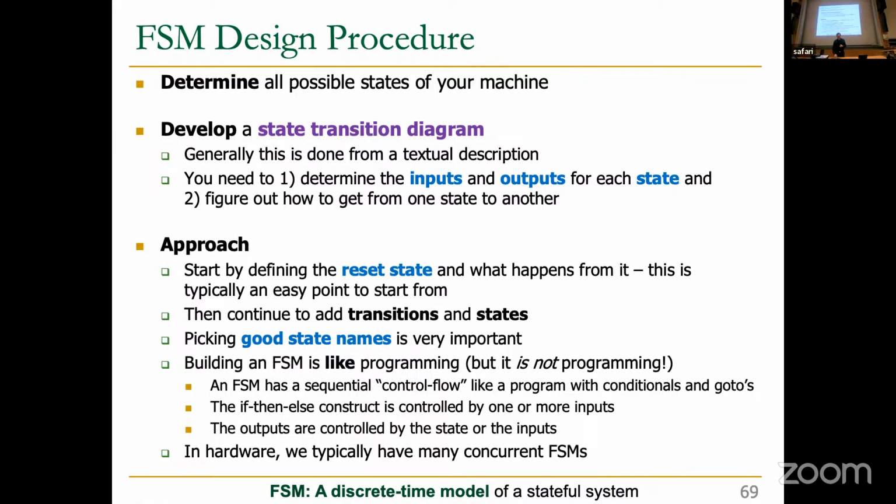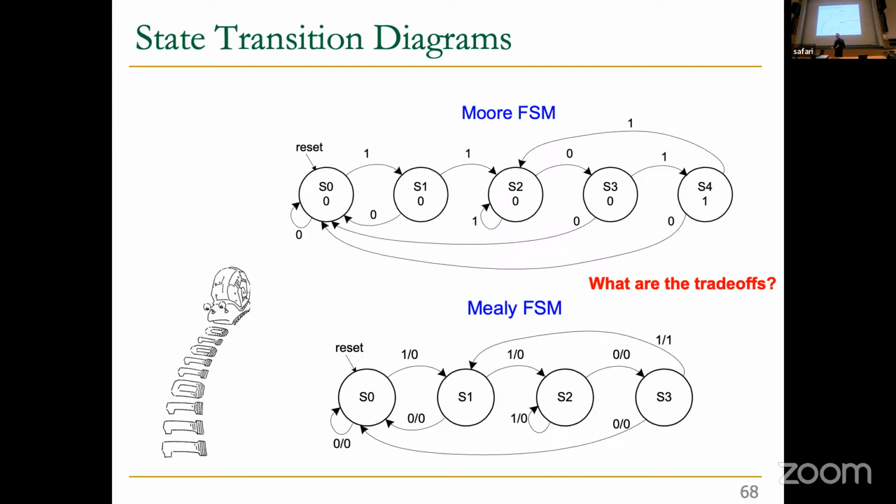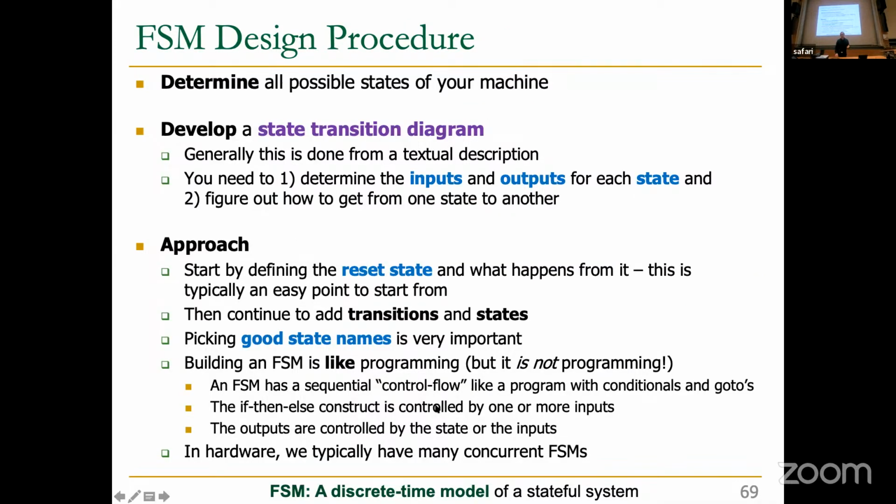Reset is very important. And as I said over here, I don't know if I want to go through all of these, but I will mention that building an FSM is kind of like programming, right? Like what you've done in modeling the brain of the snail: if the input sequence is 1, 1, 0, 1, you output a 1, right? You can actually write a program that does this relatively easily, except we're doing it as a sequence of states, not as a program that you're used to. So it is not programming, basically. You're really designing a stateful system in the end.